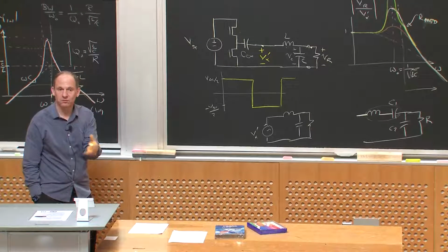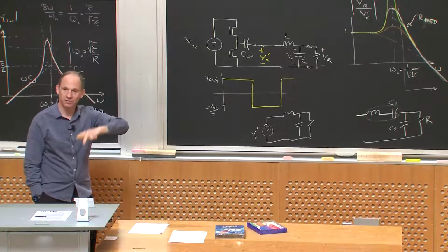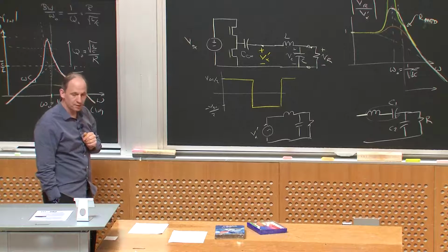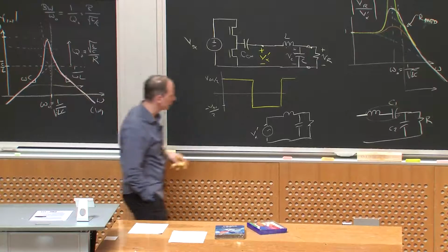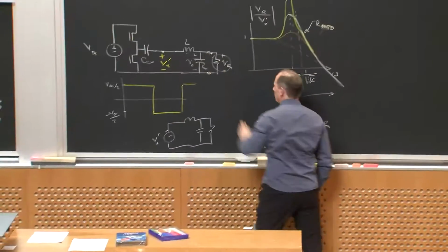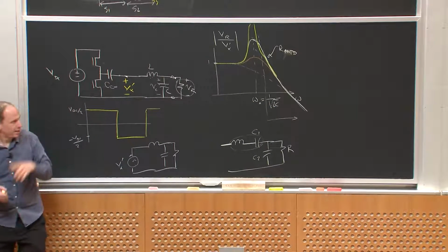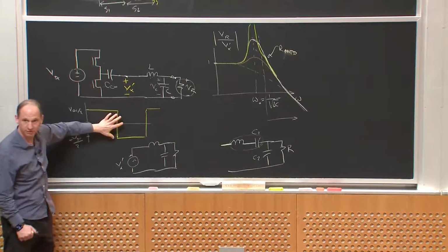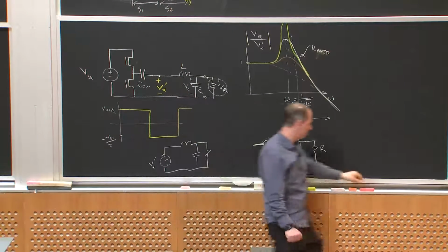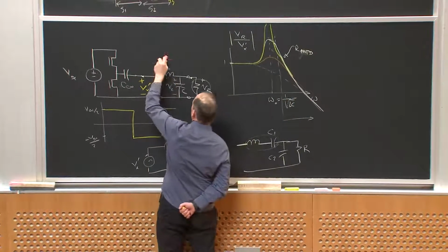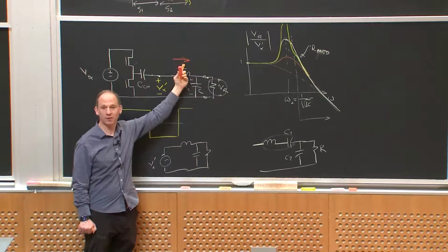Wireless power transfer, right? If I'm going to go across a link where I want sinusoidal fields. Another example, however, is just straight DC to DC conversion, right? I didn't say what this resistor was, but imagine I use a network like this one. I take DC, I chop it up, generate a square wave. If I have a high Q tank, then this current becomes sinusoidal or close to it, and that's where I make my fundamental harmonic approximation.